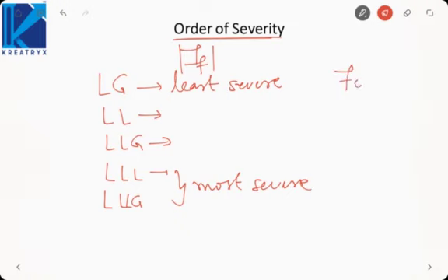So the chances of occurrence are 70%, 15%, 10%, and combinedly 5%. Okay, so three-phase short circuit faults are very rare, though they are the most severe type of fault, because all three phases are short circuited simultaneously, which will be a very rare occurrence.